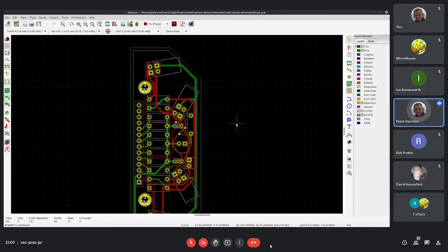So anyway, you can define your board outline. There are some constraints compared to Eagle. It's not so easy to do rounded edges and things like that. And the nodes at the ends of the lines are not connected. So if you pick up one of these lines and move it, it will not necessarily be connected. This is an annoyance, I confess, apparently to be fixed in 6.